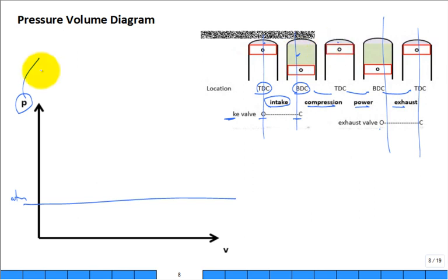That's the pressure. And it has to be lower than atmospheric pressure. Otherwise, you're not going to ingest any air-fuel mixture. It has to actually draw it across your air filter, through the tubes and ducting of your intake manifold. Maybe you have a throttle body or carburetor, has to draw it through there, but they're pretty well gone now.